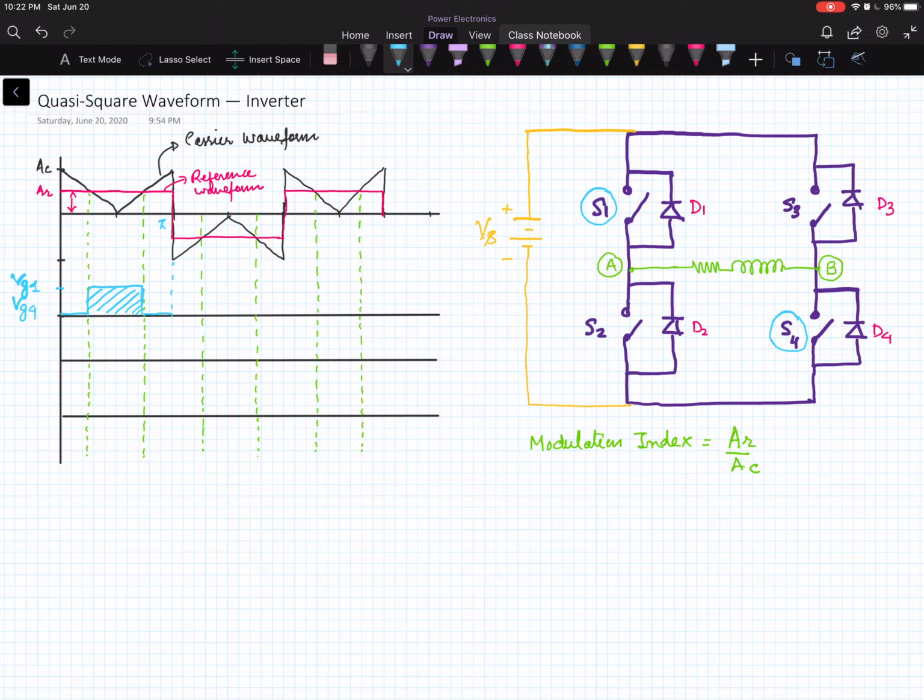Our output voltage will be equal to plus Vs. So basically our full bridge circuit is going to act as a class D amplifier. When we apply the input gate signal to switch S1 and S4, exactly same wave shape appears at the output but is amplified to the voltage level Vs.